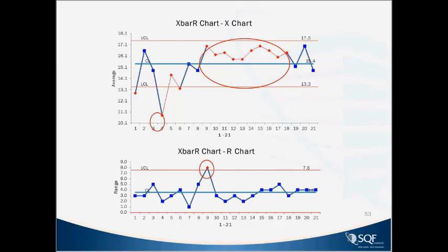You've seen the data, and in your workbooks on page 17 you've got the same control charts that I just showed you. This is a very common way of doing control charts on the line, either pen to paper or electronically, where you have the X bar and R chart on the same page and the data right below it. So they're recording the data and they're recording the ranges and the average.